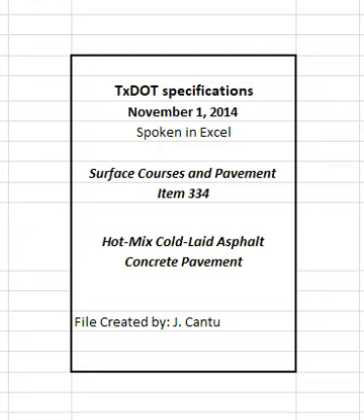2.1.2 Fine aggregate. Fine aggregates consist of manufactured sands, screenings, and field sands. Fine aggregate stockpiles must meet the gradation requirements in Table 2. Supply fine aggregates that are free from organic impurities. The engineer may test the fine aggregate in accordance with Tex 408A to verify the material is free from organic impurities. No more than 15% of the total aggregate may be field sand or other uncrushed fine aggregate.